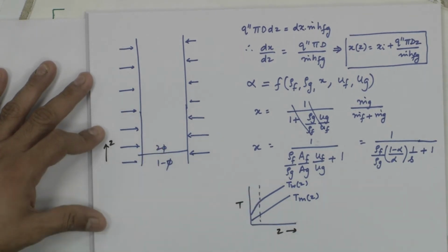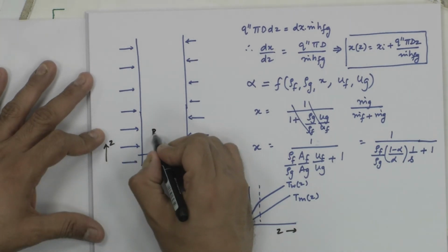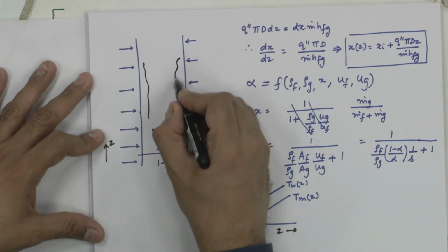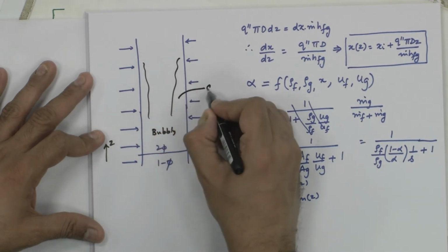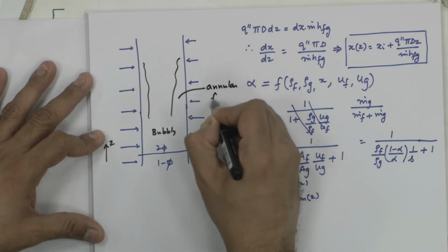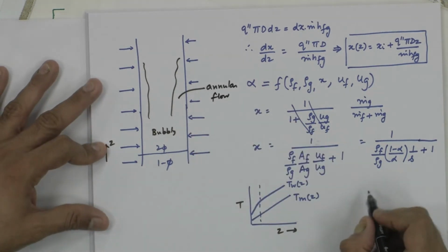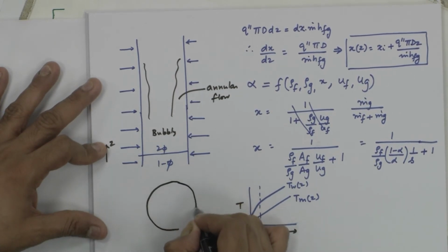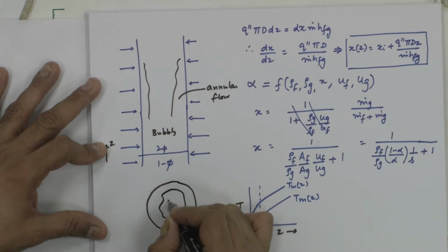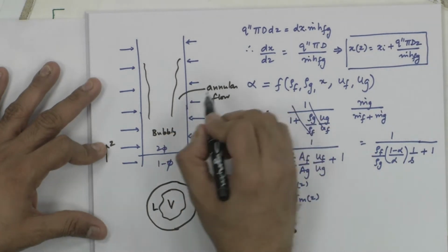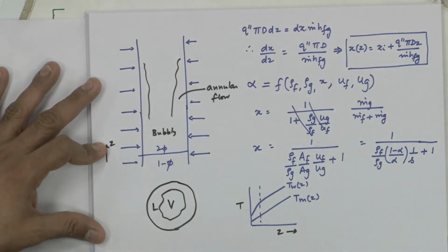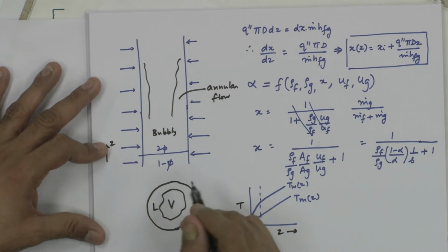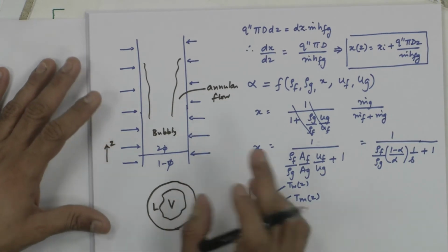Okay. Now, when you are in the two phase part, you would be in what we call as bubbly flow here, and so on and so forth, and very quickly the flow will go to what we call as annular flow. Annular flow represents the situation where you have vapor in the core and liquid at the wall. This is unlike film boiling, where you had vapor in contact with the heated surface and liquid away from it. So, we are talking of good heat transfer.